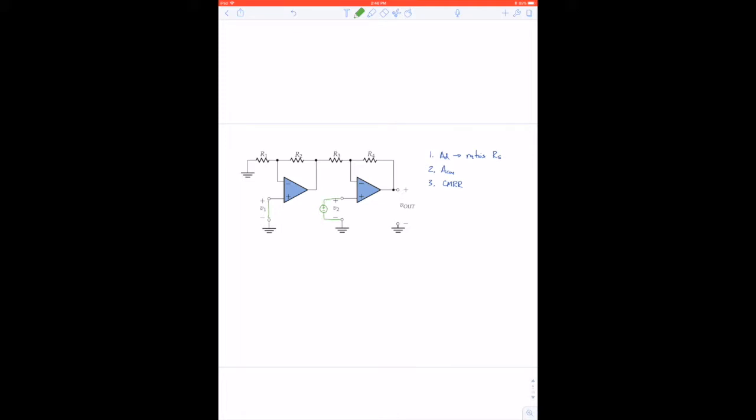and then put our test source, V2, onto the second op-amp. And when we do that, the first op-amp on the left you can think of either as an inverting or a non-inverting configuration with the input set to ground potential. And either way, the output will then also be at ground potential. So this right here will be 0 volts, right?